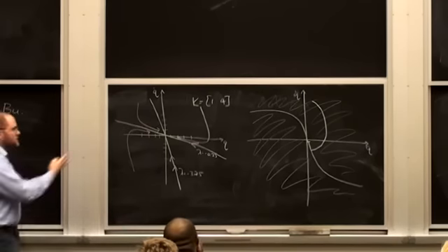Anytime, yeah. Was there a good reason we just explicitly said we want to do linear feedback there? Like we could have done like x1 times x2. Good, yeah. It's because, well, there's a lot of good reasons. So it's because then the closed loop dynamics are linear, and we can analyze them in every way, and including making these plots in ways that I couldn't have done if this was nonlinear.